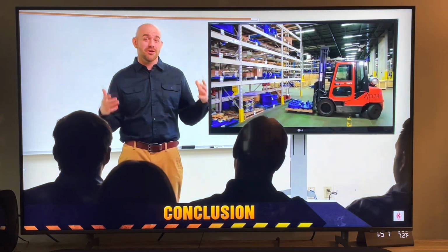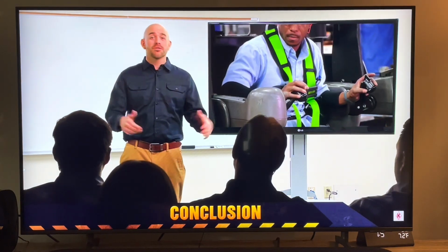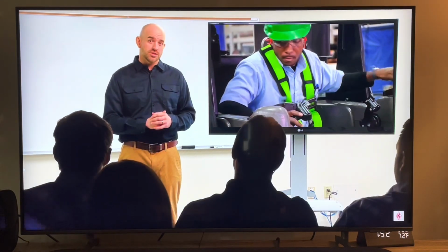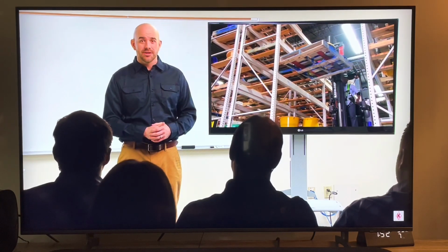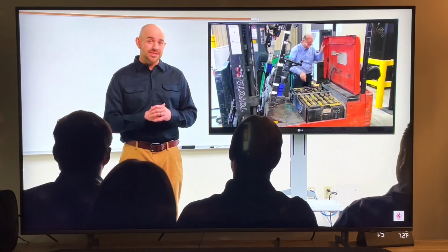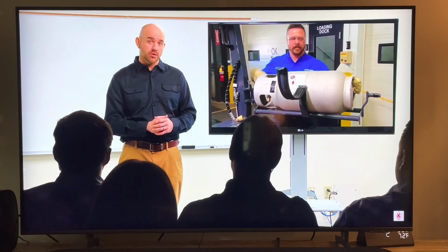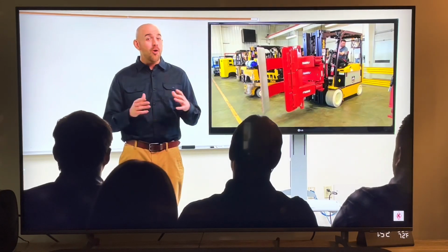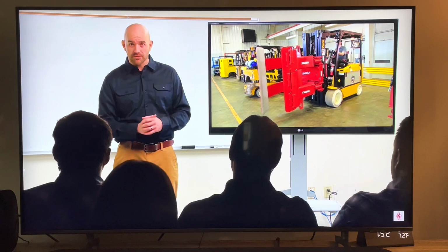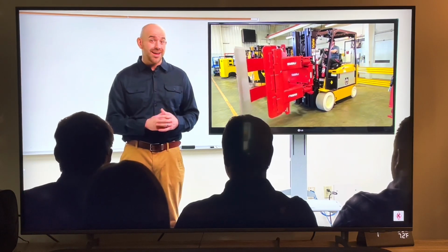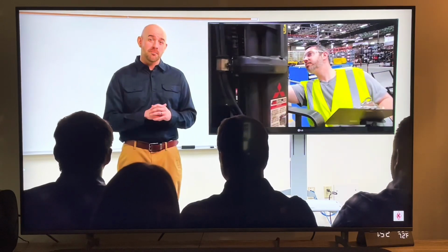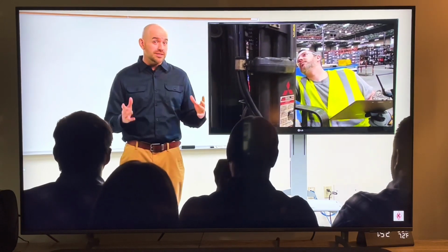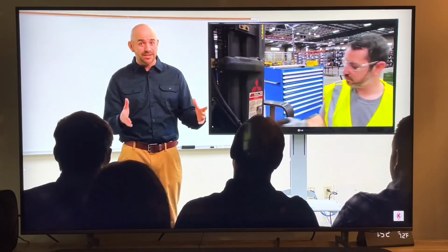Forklift safety may involve a lot of factors, but knowing the controls and limitations of the units you operate and keeping them in mind will help you work without incident. Make sure you understand how to safely recharge or refuel the forklifts you're authorized to operate. Only install attachments or modifications if they are approved and the lift's capacity is updated. And take a proactive role in the maintenance of your forklift, reporting defects before they become deadly hazards.